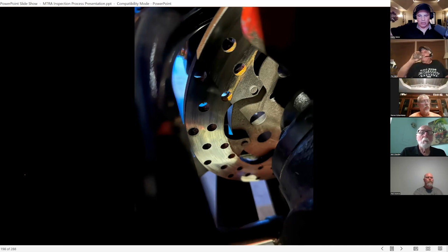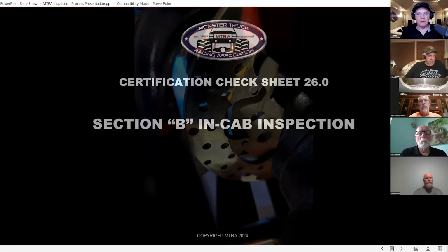It comes out in a strip. It's actually not all that uncommon a failure. You'll see something that looks like a glowing piece of flat stock out on the track, and that was a rotor that just went through the caliper, was straightened out, and got spit out. So you definitely need to make sure that all the bolts and all the hardware are there.